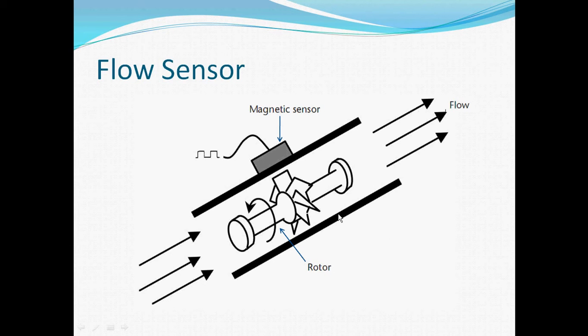An example of a flow sensor is the turbine flow meter. As shown in this picture, the turbine rotor is mounted in the center of the pipe and rotates at a speed proportional to the rate of flow of the fluid passing over the blades. The turbine blades are normally made of a magnetic material or ferrite particles in plastic so that they are unaffected by corrosive liquids.